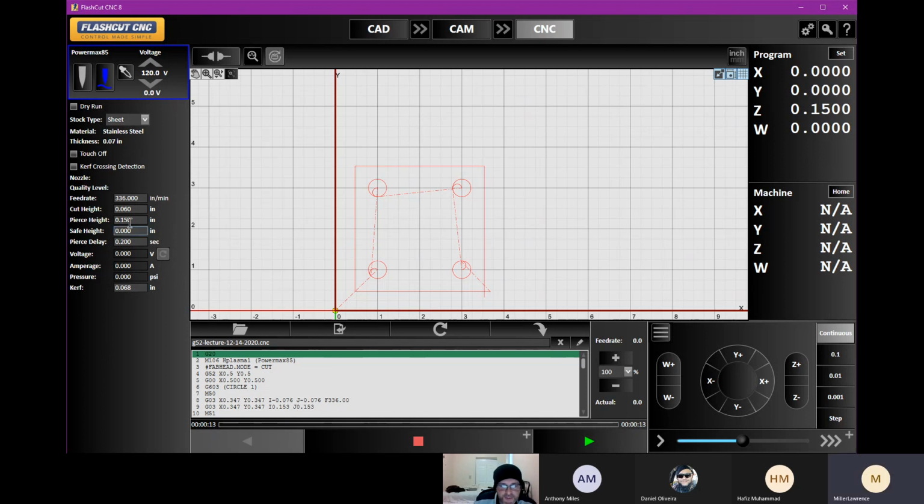Now we've got to pick a Y coordinate that is high enough to give us room to make cuts, maybe put like a quarter or a half inch in between. I'm looking at this and I see, try to keep it whole numbers, so we'll say 4.